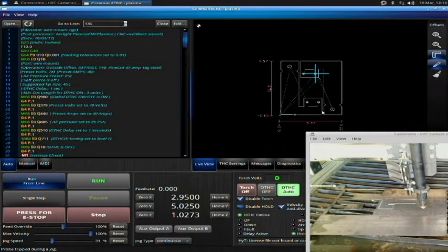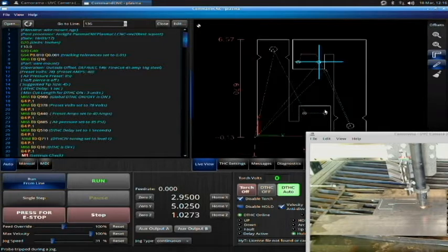Usually, that might happen, say, if you had a problem with your tip, or say your air pressure was off for whatever reason. The machine might sort of cut, but it doesn't quite cut the hole the way you want it. You can go back and recut something. So for instance, with it pulled out of the run mode, I paused it and stopped it. I could go in here and say, well, let's go back and recut this hole right here.